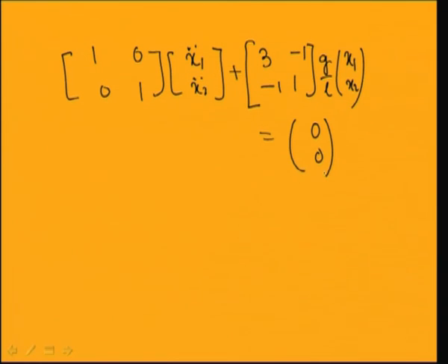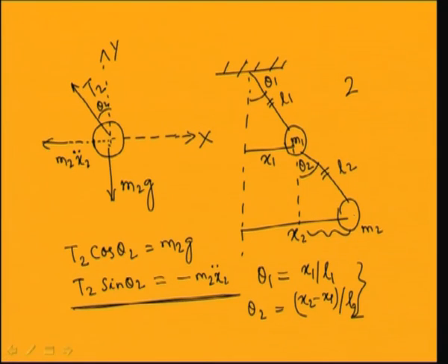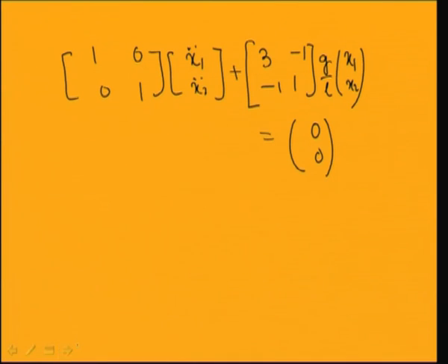Now, proceeding in the previous way, you can find the normal mode vibration of the system. In case of normal mode vibration, both the masses, this m1 and m2, will move with the same frequency and will pass the equilibrium position at the same time. So, this is the normal mode we are assuming, and the actual free vibration will depend on the initial conditions. That thing already we have seen. So, now I will tell you another method to determine the free vibration response of the system. We can determine the normal modes from the eigenvalues of the system.